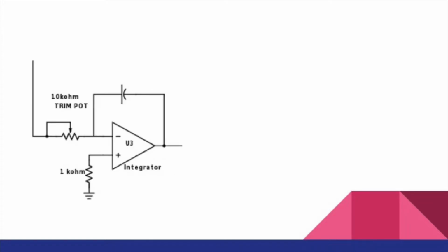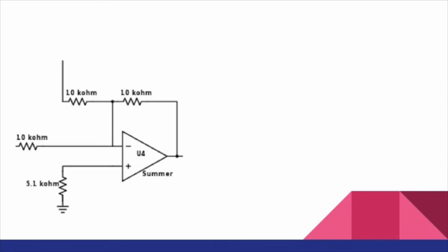The integrator continuously evaluates the error and calculates the area under the process variable using the difference between it and the set point, all while the error is not equal to 0. In such case, the proportional gain alone is added in the summer. The summer adds the values of the PI outputs.